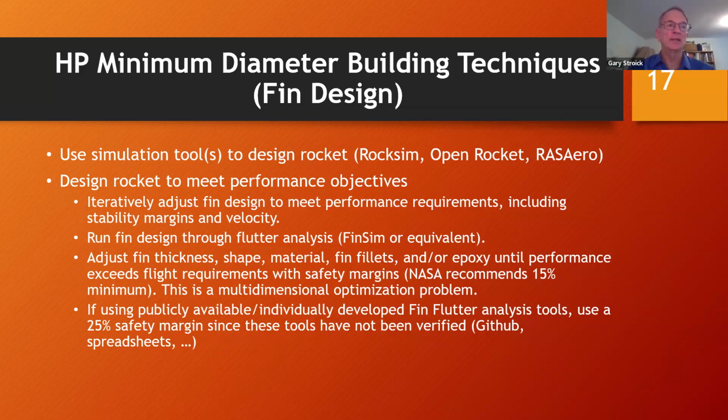But what that allows you to do is to provide the parameters of the fin in this particular tool and the size of the airframe that you're putting on it. And that you can provide the fin thickness, the shape of the fin, the material that's being used, the size of the fin fillets and the epoxy that's being used. And then you can model that fin during the flight, putting in the maximum velocity you're going to hit and at the altitude you're going to hit it. And then you can model that and determine, well, is my fin going to hold up?